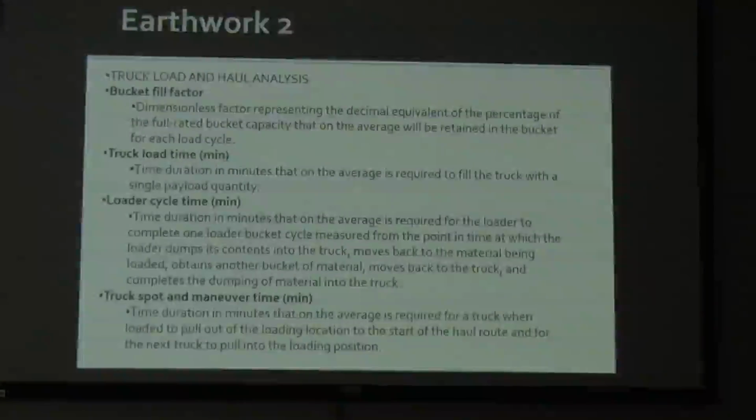The loader cycle time is the time duration in minutes that on the average is required for the loader to complete one loader bucket cycle, measured from the point in time at which the loader dumps its contents into the truck, moves back to the material being loaded, obtains another bucket of material, moves back to the truck, and completes the dumping of the material into the truck. So the loader cycle time is from point A to point B and all the way back to point A.